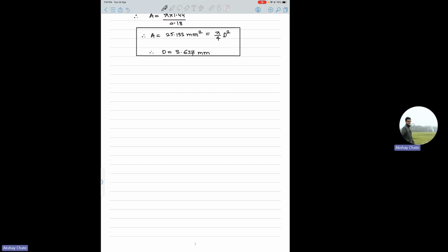Why do you do that? Because when you sit at the tip of the electrode, I mean, you can't sit there, it will be very hot, but assuming that you are able to sit there, you will observe that material is coming from one direction, melting exactly at the bottom of your electrode, and then leaving the electrode. So by selecting the frame of reference as the observer sitting at the tip of the electrode, you solve that relative motion problem.